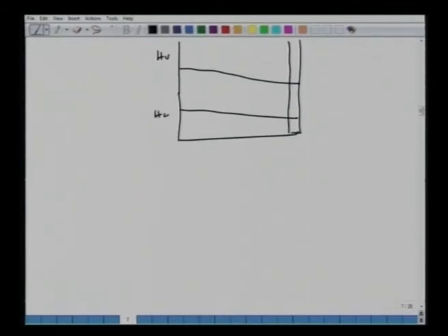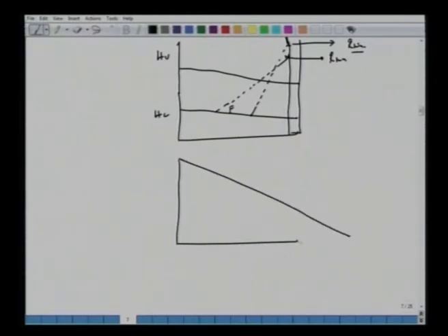So one has to do some inspection to find out the minimum amount of solvent. Similarly, if we have the tie lines, say case 2, where the tie lines are downward in the other direction. So if you have the tie lines like this, in this case also one has to extend. So if you have this RNP and YS, if you extend like this and this, so in this case you can make out that the tie line which passes through F, if you extend, this will give us del min.